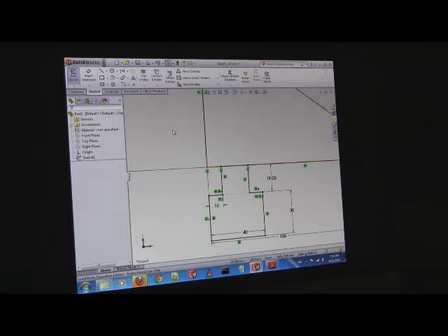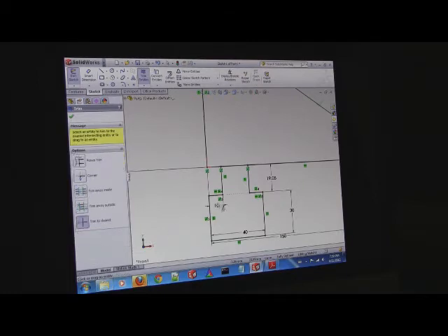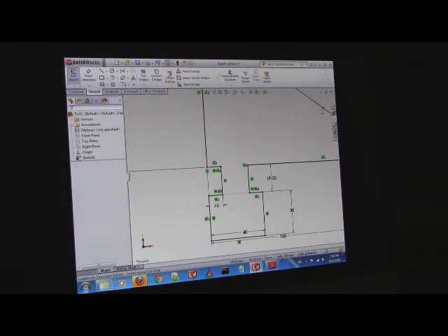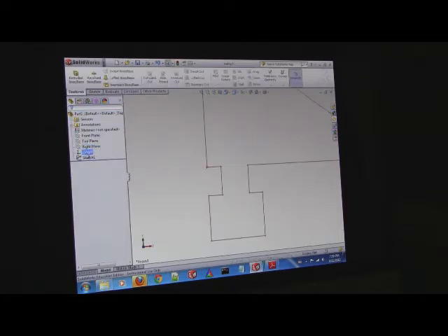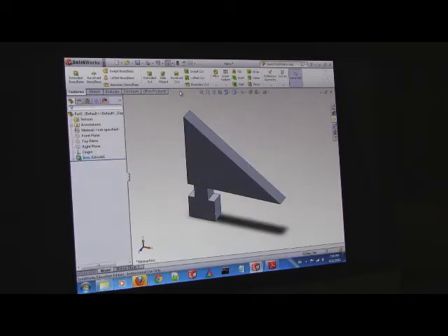Power trim, yeah. So this right here, trim entities. And now don't do power trim. Do trim to closest. This bottom one. And then press there and it goes away. And now it kicked me out of my sketch. So I have to do sketch, extrude base, and then do 19.05. Then we're good.